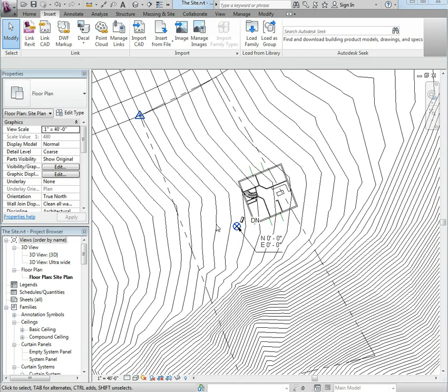Okay, what I did is I paused the video recording and I've basically loaded in center to center. This is the way that it would come up normally. And notice that the house comes in rotated. The coordinate systems haven't yet been linked, so Revit just brings the file in so that the linked file's Project North, its internal coordinate system, is lined up with this file's Project North, or its internal coordinate system.